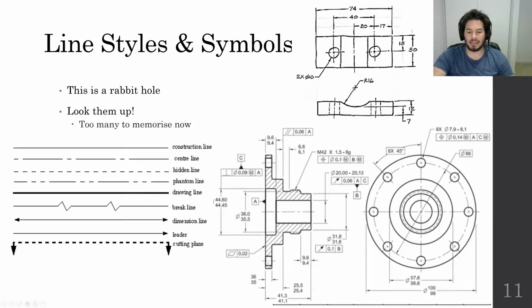Something that this is missing. So this is a section view, and we will talk about section views in the future in, again, 1 or 2 slides time. It's basically telling me, imagine if you cut this thing in half, and I was showing you a cut in half section. What you would normally do is denote the cutting plane that you cut with one of these styles of line. And they haven't done it in this drawing. It's probably redundant to have done it. They probably thought it added more confusion than it saved. But just so you know, cutting plane is a different type of line.